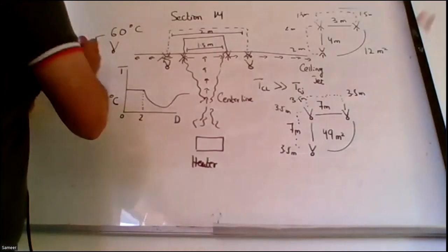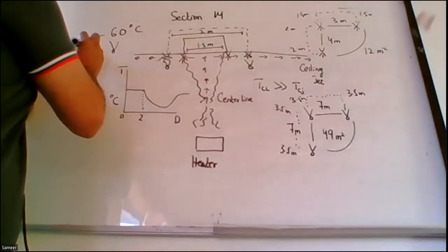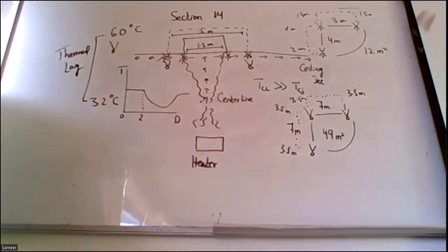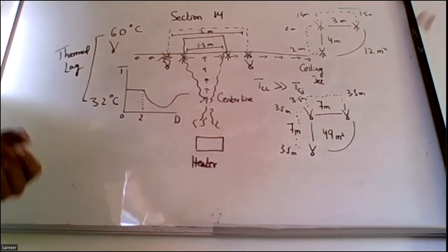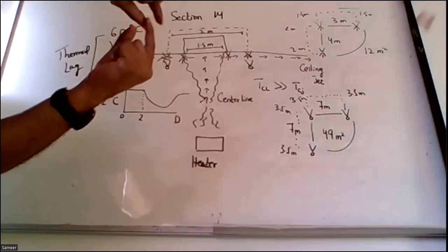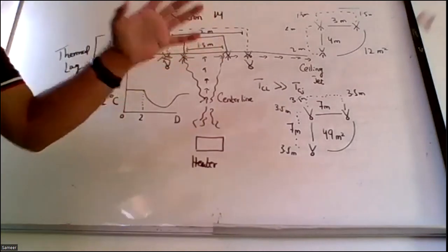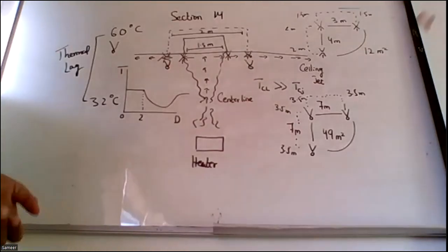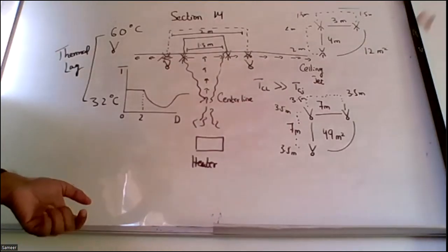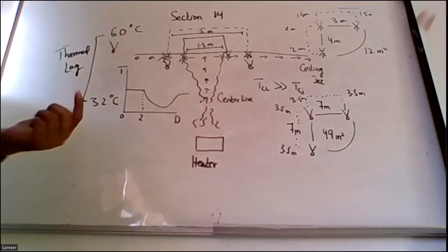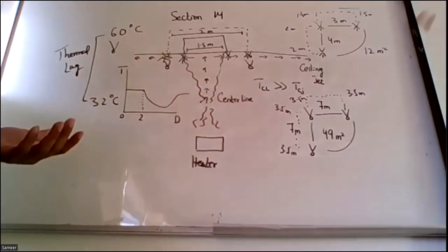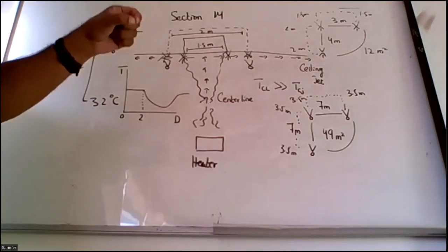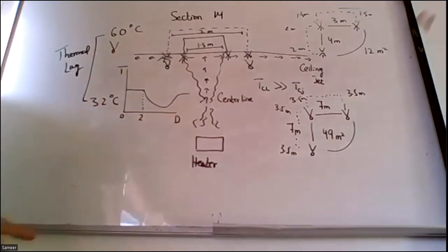This feature is known as the thermal lag feature. Fixed temperature and rate of rise heat detectors have one collection point. At that collection point, if the temperature reaches 60 degrees Celsius, the heat detector operates, but when I enter the room, I find it is 30 degrees Celsius. Why is my heat detector operating? Does it mean my heat detector is faulty? No, heat detectors are the most reliable detectors with the lowest false alarm rates. The only cause is the thermal lag feature, because the heat is being collected at one point, and at that point the temperature is increasing continuously.